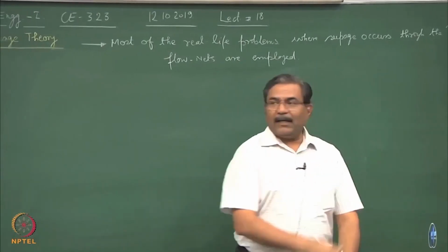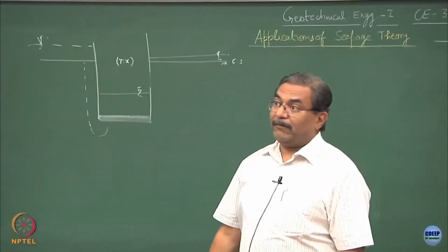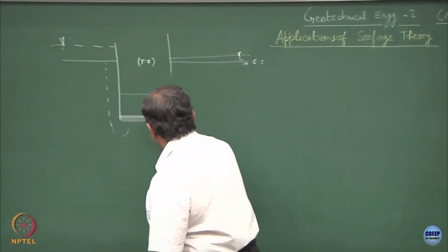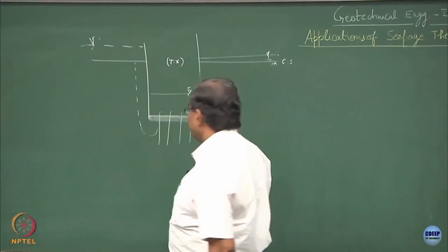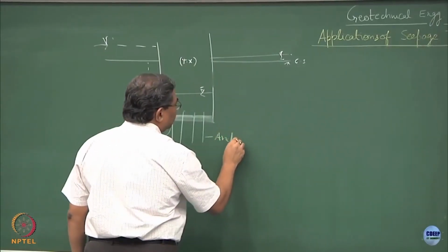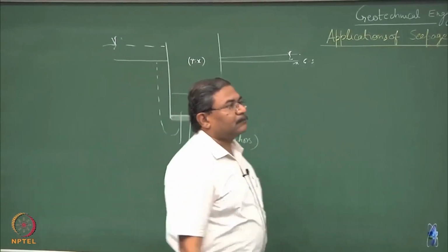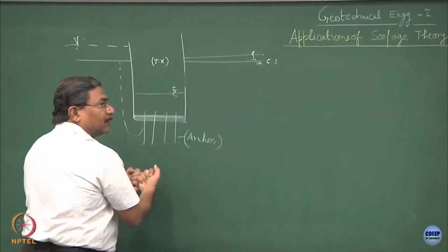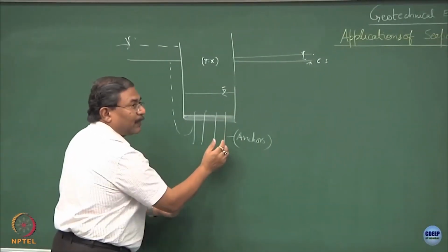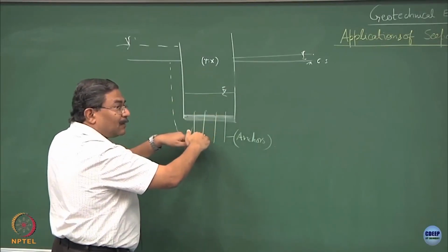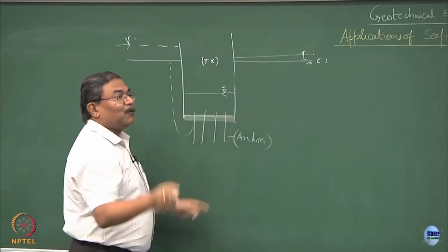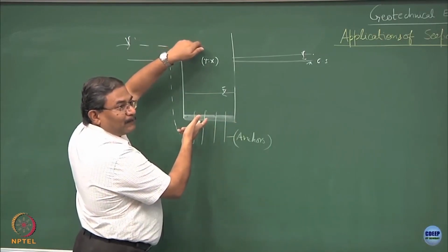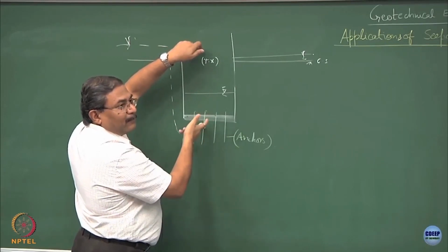Now, if you are not satisfied still, suppose the water table is very close and dynamic situations and what not, do proper anchoring. What are anchors going to do? They are going to hold the raft always, and this much of the pressure is going to get added up to the weight of the system, because 9 kilonewton per meter cube multiplied with the x is not going to compensate for 25 into x value, sorry, 16 times x value.